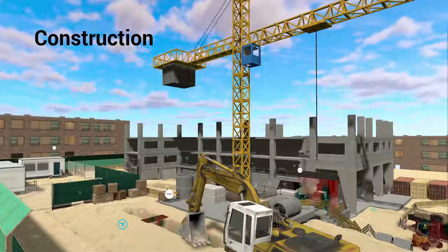And then once construction is completed, the design model can be updated to reflect the as-built condition of the model. This would typically be done via reality capture, and then an extraction from the point cloud of all the components. This is perhaps the least developed part of the process, but it is a crucial step for the next part.